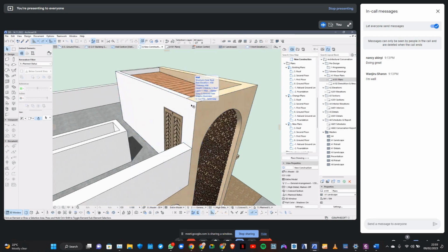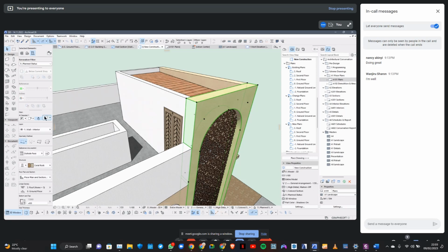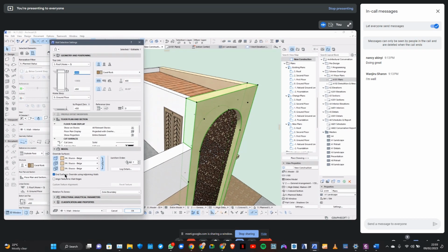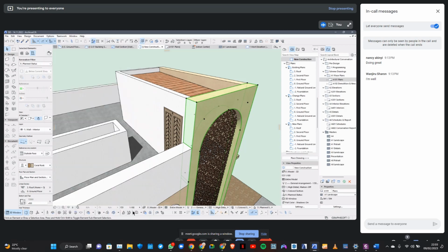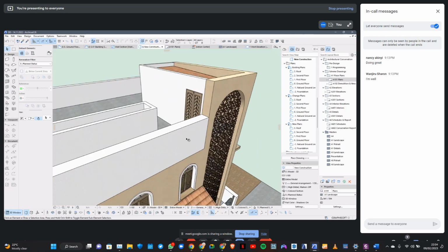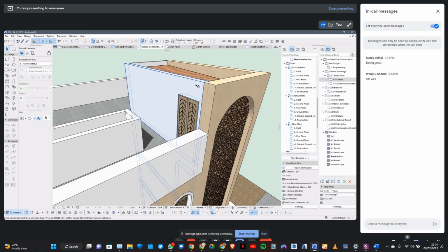That's because of something we call overriding the edge. So on this edge here, there is this check mark I've set: I want this end surface to be overridden using this adjoining wall. But if I uncheck that, you see, now it's beige. It was white because this adjoining wall was also white.